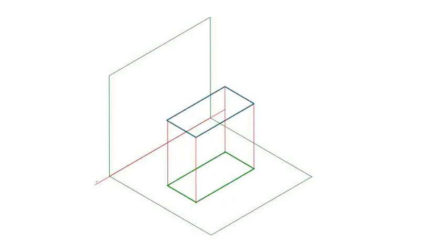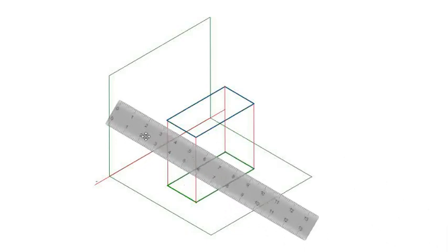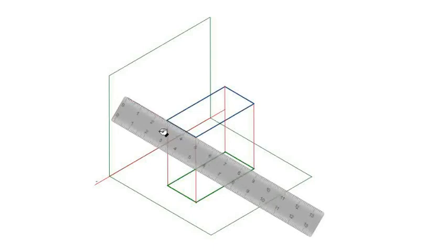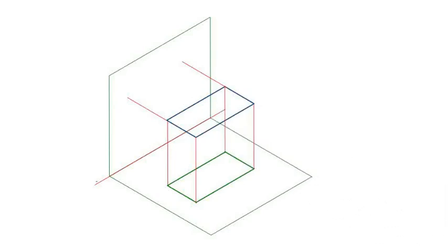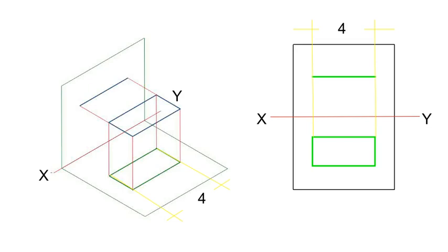Step 2. Project downwards to get the front view. Step 3. Notice how the rectangle appears distorted in front view, but remains true in the top view. This method applies to all plane figures, circles, pentagons, hexagons, etc.